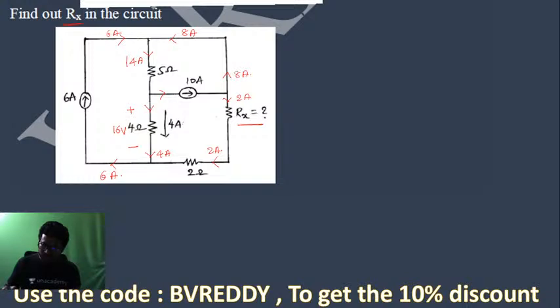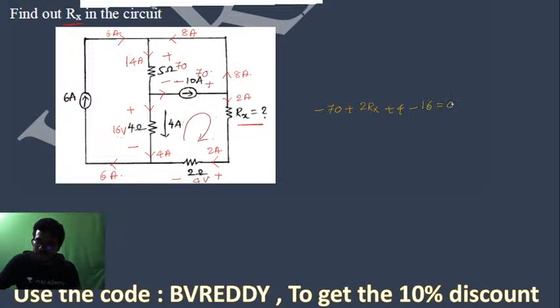Let's try it now. Now I can get this voltage, how much is it? 4 volts. And this is 60. Then how much is this voltage? 70. This voltage is also the same, 70 volts only. Yes, I can apply the KVL in this loop. If we apply the KVL, tell me what we'll get. This is minus 70 plus 2 into Rx plus 4 minus 16 equal to 0.